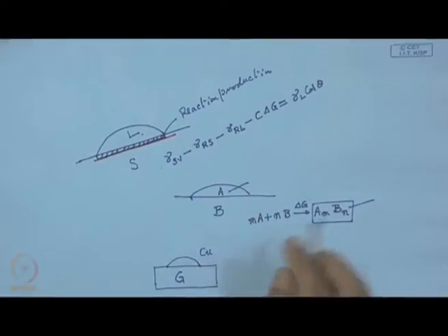Now, what can be done, as we have mentioned already, to promote the reactivity? We have to add one reactive element. Say for example, titanium is the reactive element. So, this is now copper solvent, titanium solute. That is a combination which can now act to promote wetting, and that can go in a very favorable way.